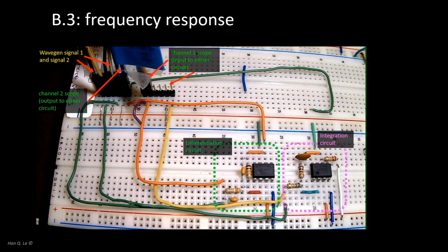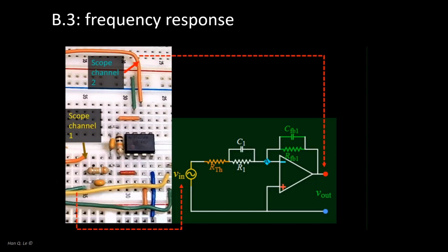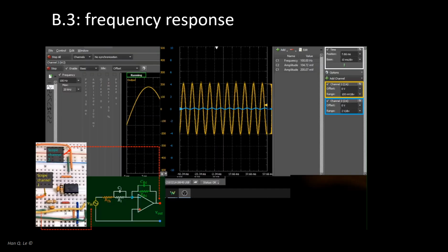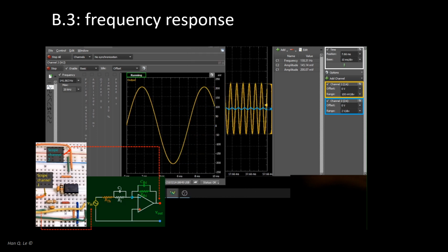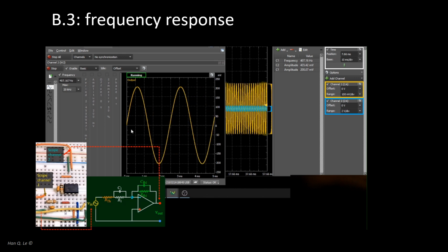Here, we encounter the concept of frequency response again, which was done for the op-amp voltage amplifier in Lab 4. The behavior of the gain versus frequency appears to be opposite in this case. The circuit favors high frequency over low frequency. This behavior is also known as a high-pass filter, a device that selectively lets the high-frequency signal get through with higher amplitude than the low-frequency signal.